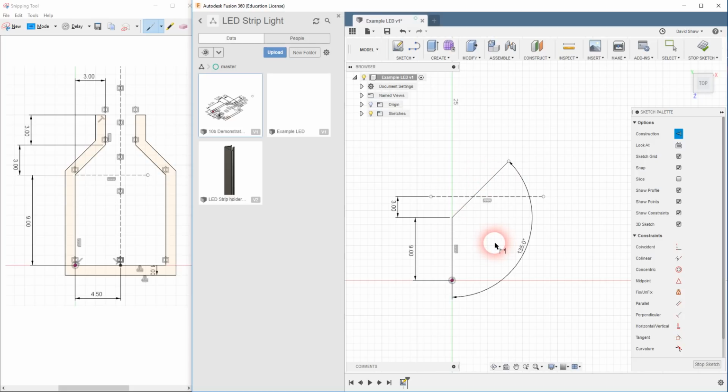Okay, now let's get another line in here. I'm going to do this vertical line that I can see over here. So let's come to the line tool again, and actually that's just snapping at that point right there. Now that happens to be on the grid, which is making my life easy, but just to show you a different way of doing this, because I want to snap onto the end of this diagonal line, what I'm going to do is escape that tool, the escape key on the keyboard.